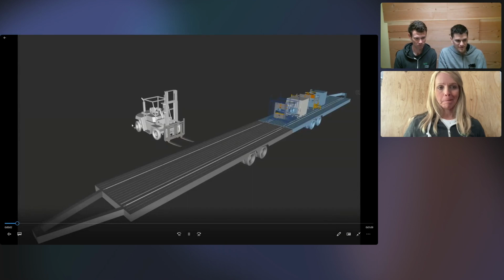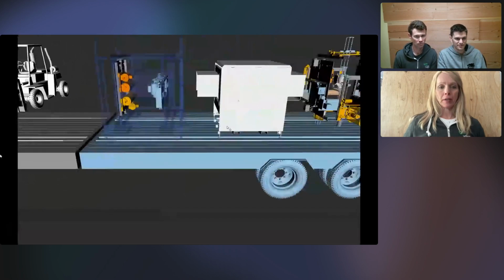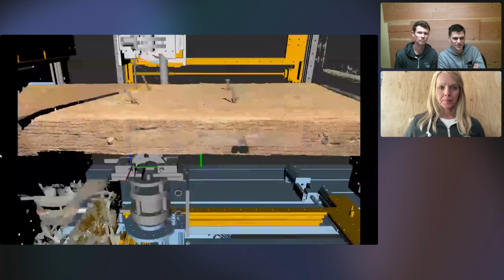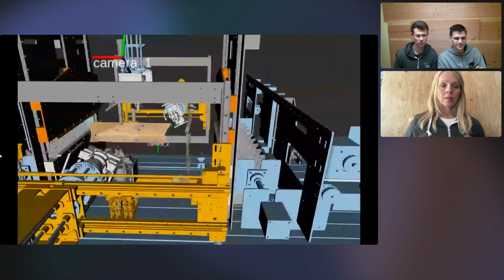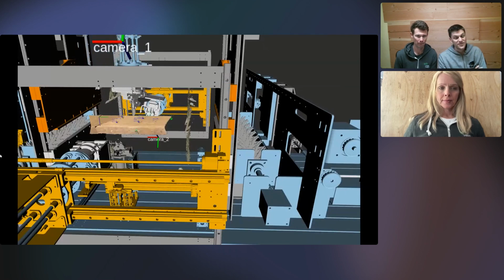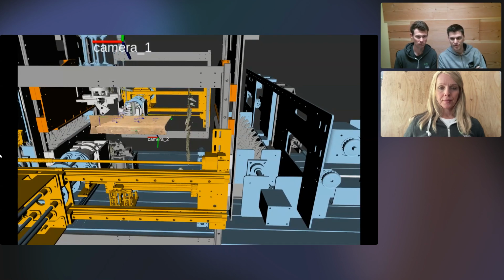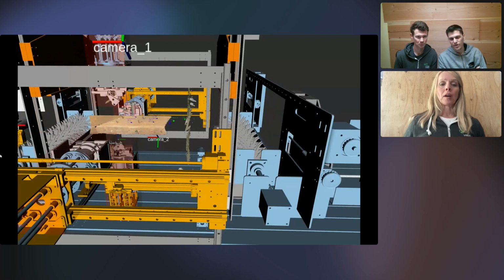Here we go. So this is all of the URDFs combined in our system as the robot runs, and all of those 3D models you're seeing are specified in various URDF files, and you can see the robot grabbing at virtual nails and looking at virtual wood, and all of those joints being commanded to move to different positions. So this is tremendously useful for me as a software engineer because I do most of my development on my laptop without being connected to a real robot, just moving these 3D models around and making sure that it looks like what I would expect to happen in the real world before I go and test on the real robot.